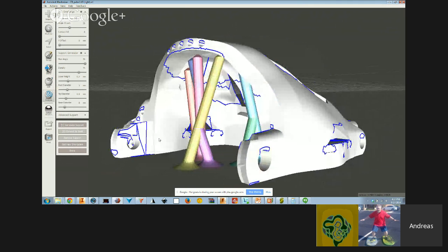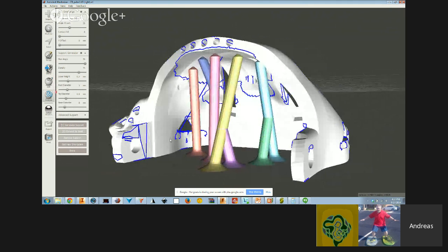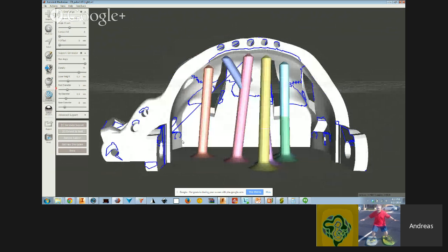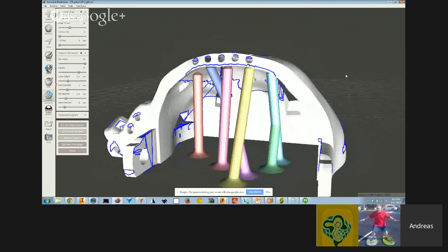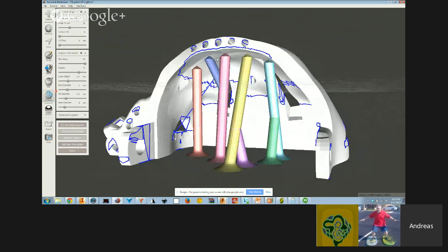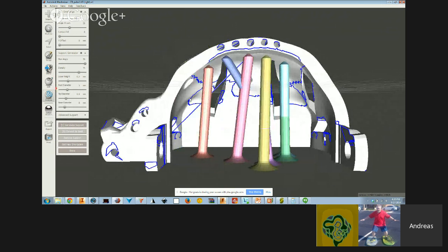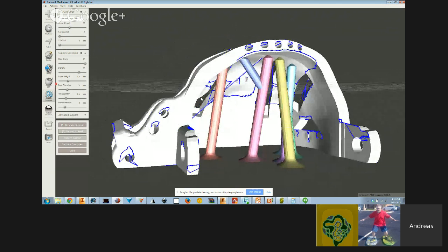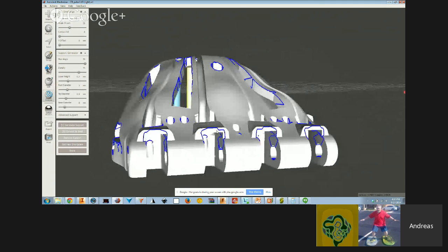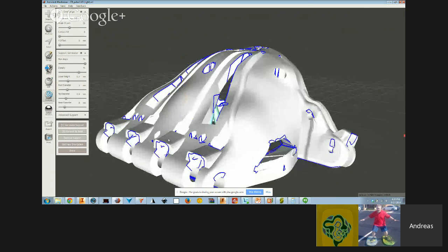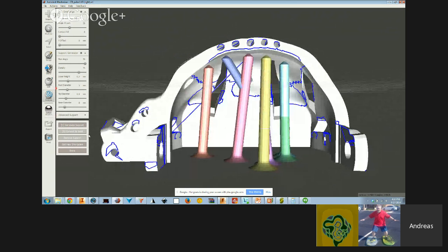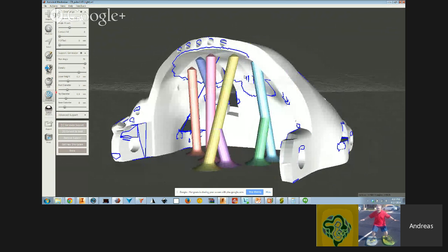This is going to save more time, and looking at it, you're like, this is a good print, because really the only overhang that I would be worried about is up here, where the angle starts to get really sort of parallel to the print bed. They'll probably survive these little holes right here, and some of this stuff here, that would print, right? Yeah. So in this case, I'd probably be more comfortable. I could add a few more, maybe back here, but I'm pretty sure that it would get through those.